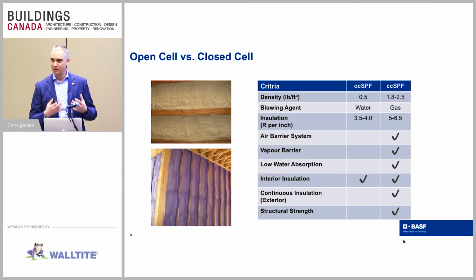And so the refrigerants, they're in the resin component. When the foam components react on the wall, they create heat, and that causes these refrigerants to turn into a gas form, and that's what helps the foam rise, and that's what actually gives it the higher R values that you get, because it's got this refrigerant in there that's giving a higher R value per inch on that foam.